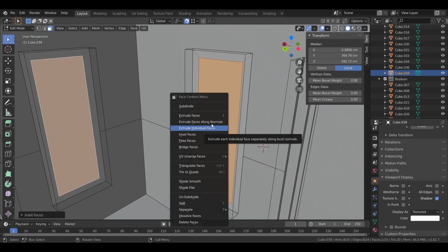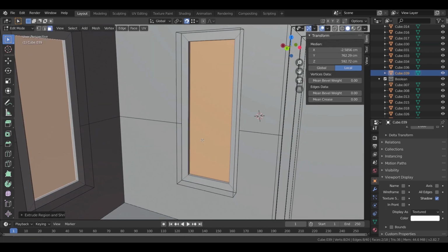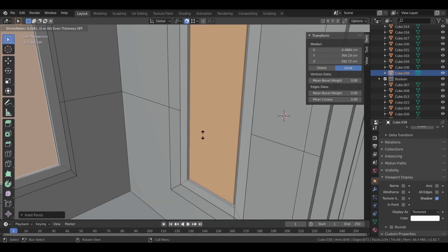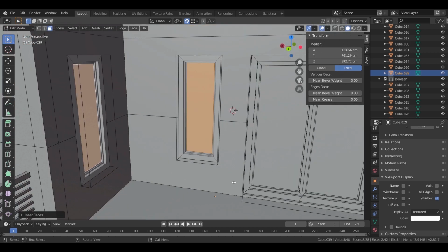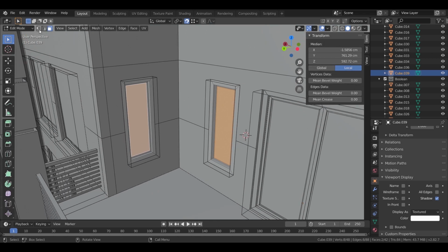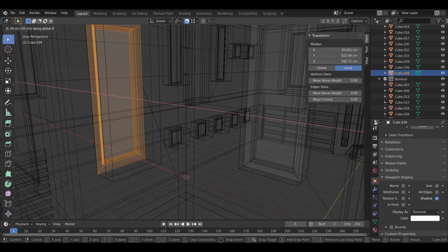Now, while selecting the face, press I and insert by 10, then extrude along normal to inside by 5, after that, insert faces by 2, extrude them again by 2, and finally inset by 2. Move the windows to inside.